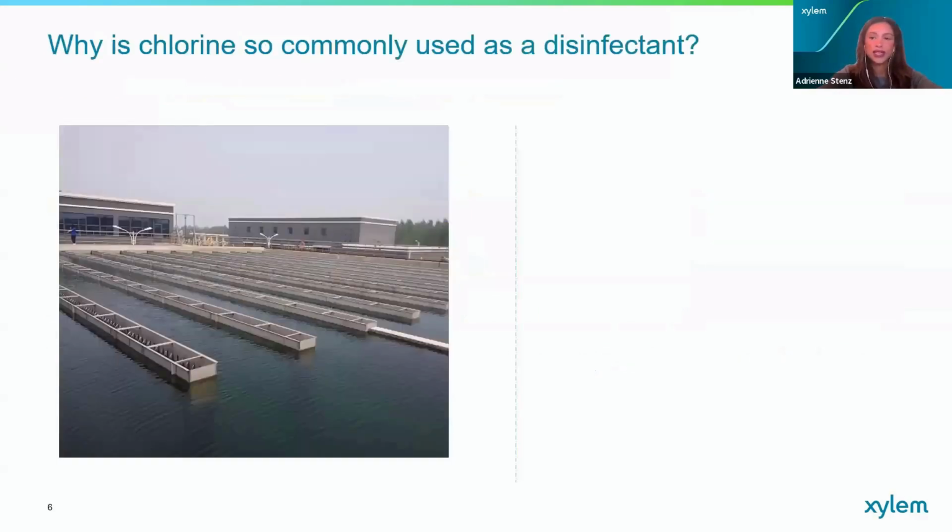Chlorine is the most common disinfectant used in public water systems for several reasons. First off, it's easy to obtain. The process for manufacturing chlorine only requires salt, which is sodium chloride, NaCl, as an ingredient. The manufacturing process is called the chlor-alkali process, which involves taking a concentrated salt brine and applying electricity to separate the sodium and chloride molecules, leaving chlorine gas as a product.